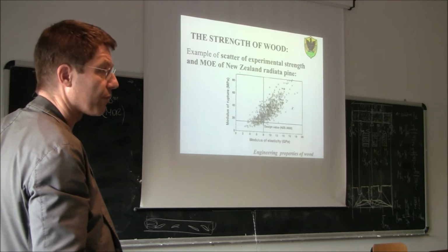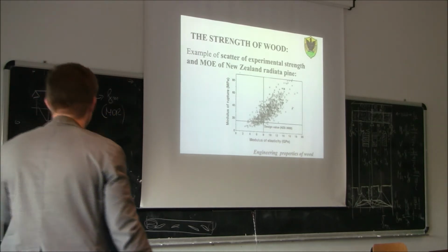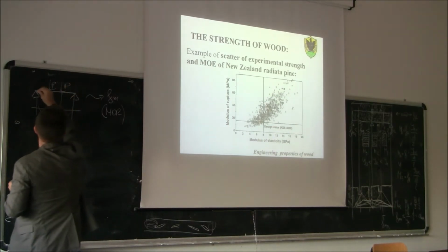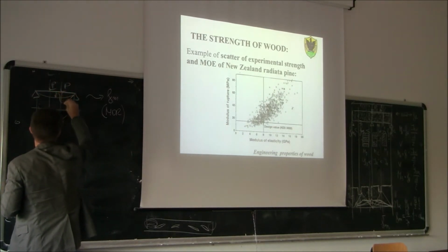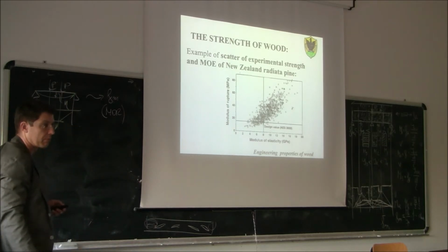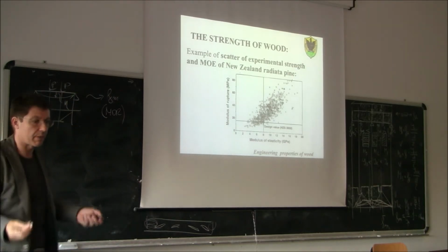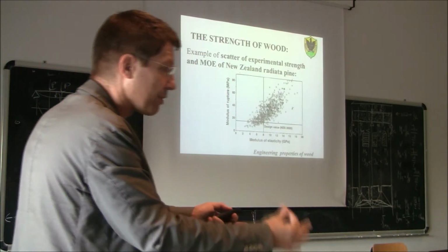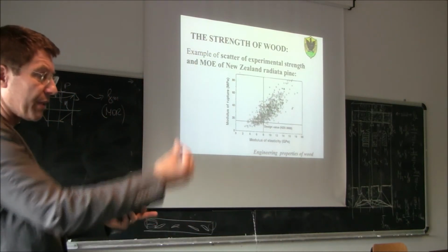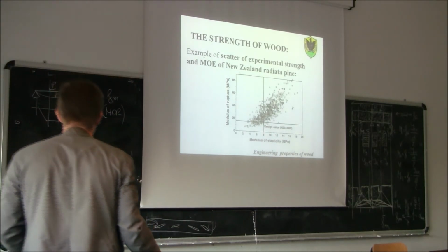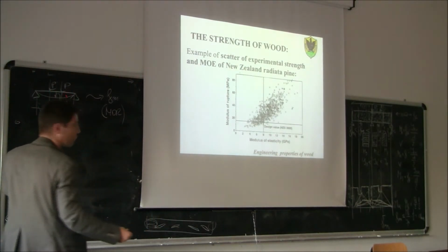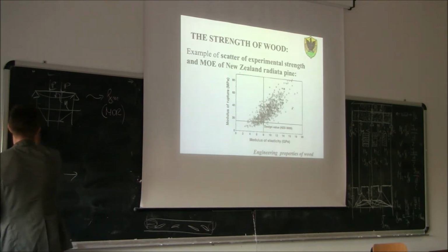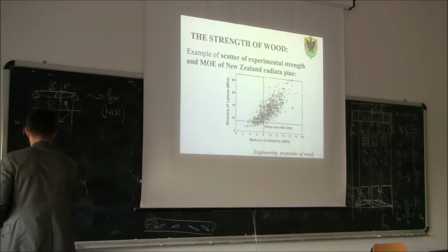How do we calculate the modulus of elasticity? Well, when we apply a load, we measure the deflection. We have, for example, a linear voltage displacement transducer, some instrumentation to measure the displacement. And we know that if the load is not high, we have an elastic relationship between the load and the deflection.